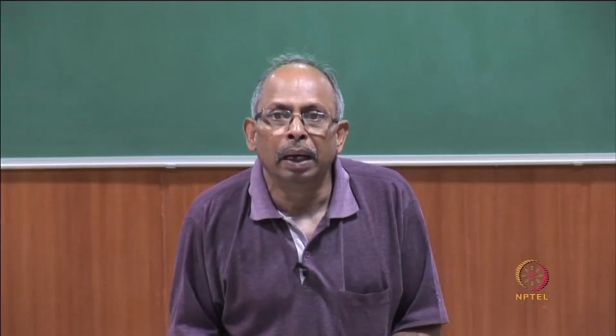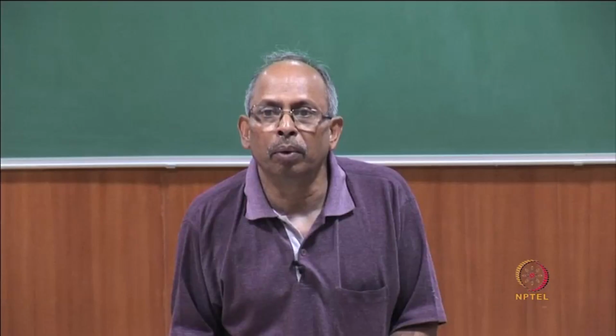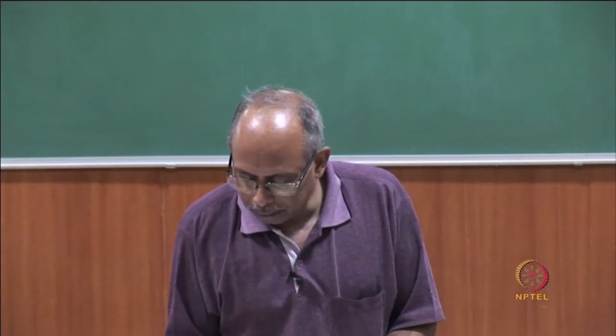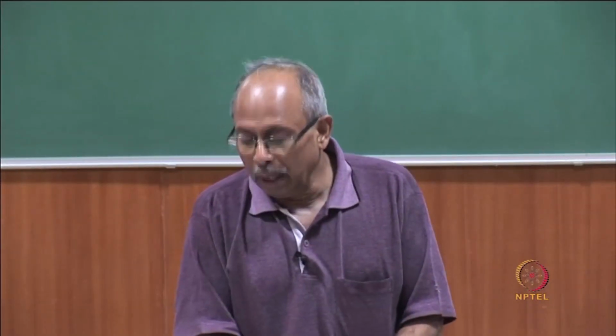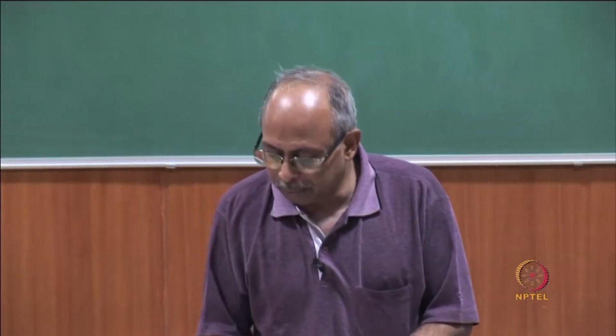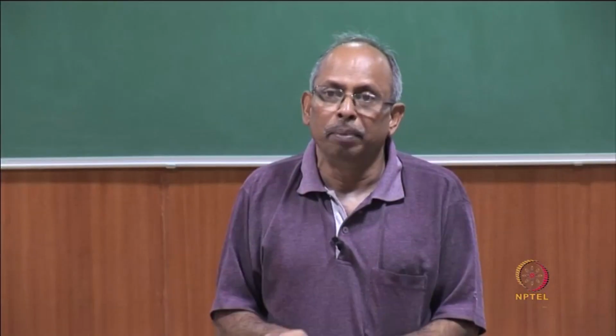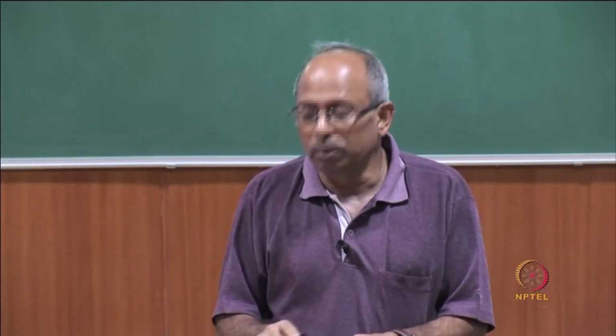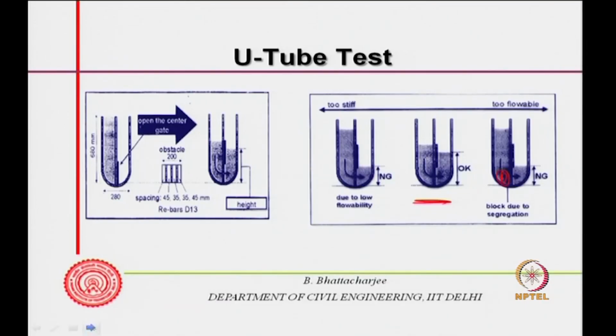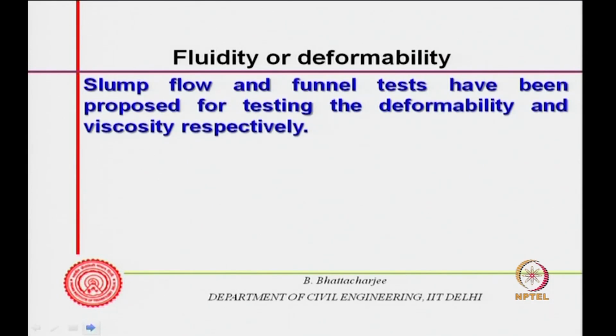Therefore, it is not self compacting. A self compacting one will have two equal heights, like water would, but it should be sufficiently close to each other. So, this is called the U-tube test.